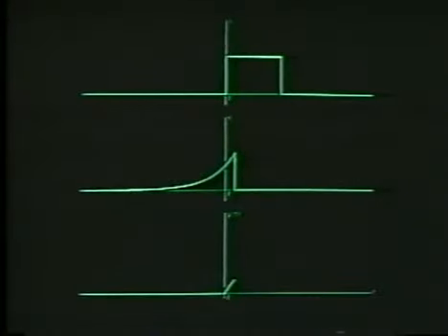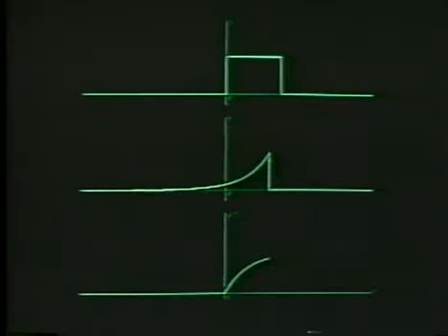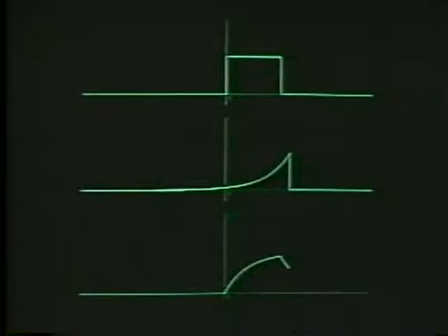Now, as we slide further, until the impulse response shifts outside the interval in which the pulse is non-zero, the output will build up, but here we've now begun to leave that interval, and so the output will start to decay exponentially.